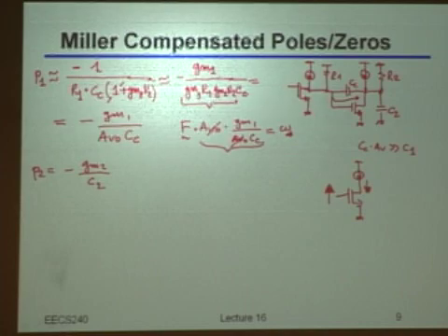After that, I have a diode-connected transistor, and so whatever I get here, it's just a wire, right? It goes to the output. So I shifted the phase, I shifted the sign of the gain. That is a very quick way to see that there is actually a positive zero. It's in the right half plane.